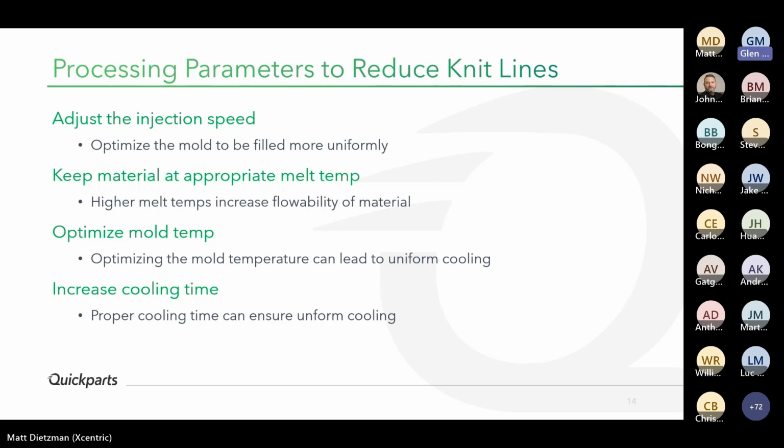You want to optimize your mold temperatures. That's different than the temperatures on the barrel, obviously. You want to keep your mold at certain temperatures. Sometimes you want to keep the core cooler and the cavity side hotter. Really just depends on the material and how your part's filling.